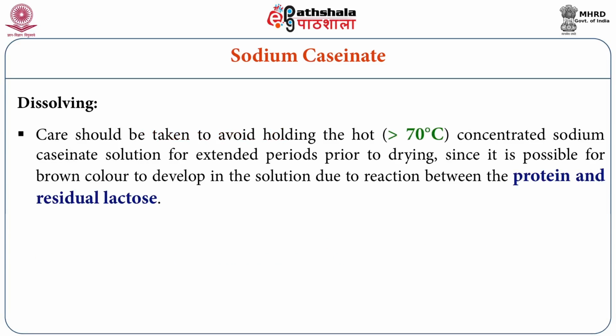Care should be taken to avoid holding the hot temperature, that is greater than 70 degrees Celsius, of a concentrated sodium caseinate solution for extended periods prior to drying, since it is possible for brown color to develop in the solution due to reaction between the protein and residual lactose. This reaction is known as Maillard browning.